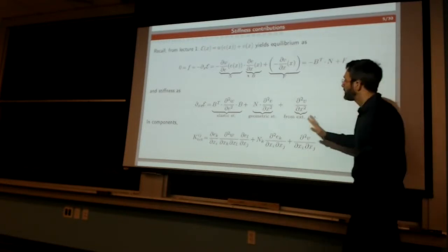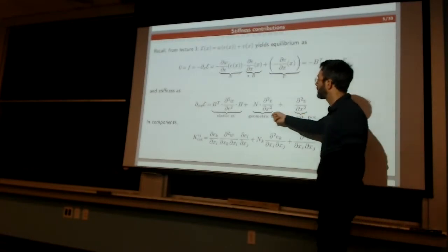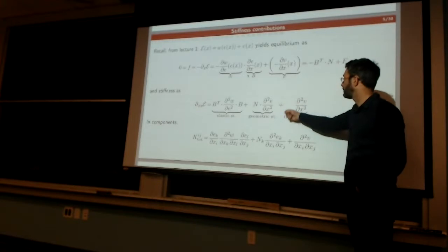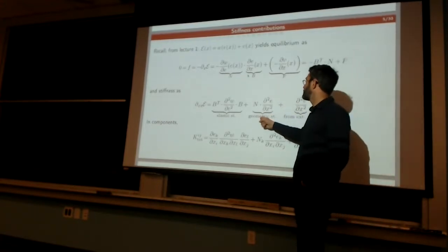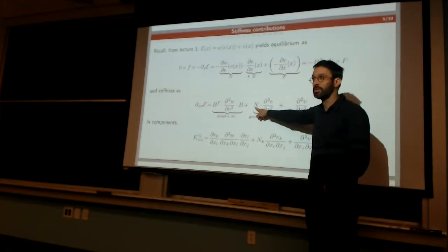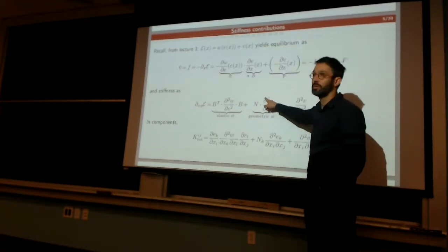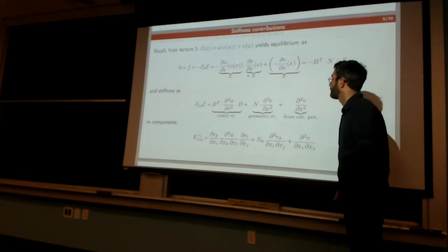Okay, so we'll see these terms. We don't need the detailed derivation. We see these terms coming. So remember that there are three contributions to stiffness, one coming from the external potential, one which is called the geometric stiffness and involves the pre-stretch, so the amount of internal stress that you have in your structures, times a second geometric quantity, which is the second variation of strain.